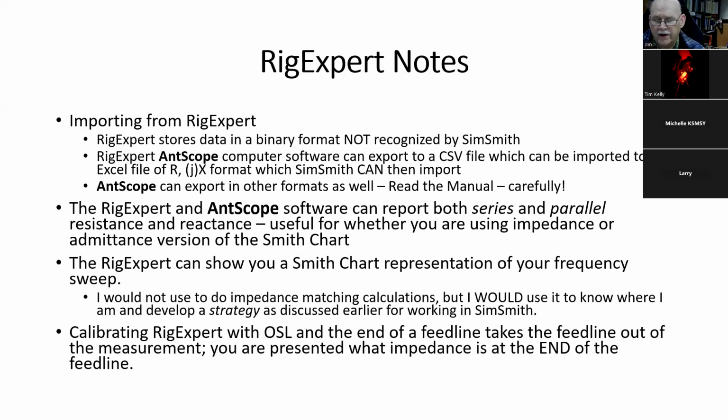If you want to do an L network with the first element being a shunt reactance, a Rig Expert by itself, forget the Antscope software, although it'll do it too, can give you a Smith chart representation of your frequency sweep. Now, I would not use that on the Rig Expert to do impedance matching calculations. It gets too small, the resolution's too lousy, and my eyes are too bad. But I would import that into Antscope and then export the data.